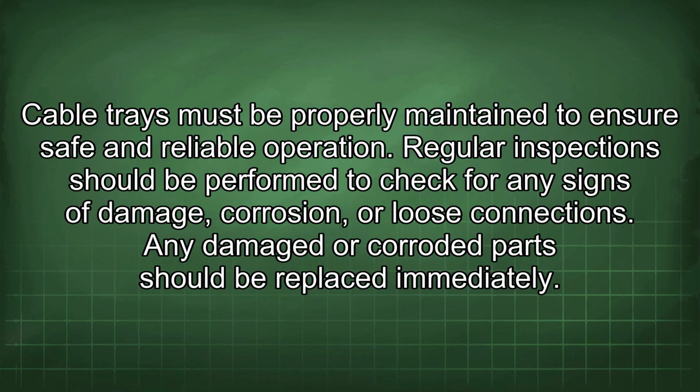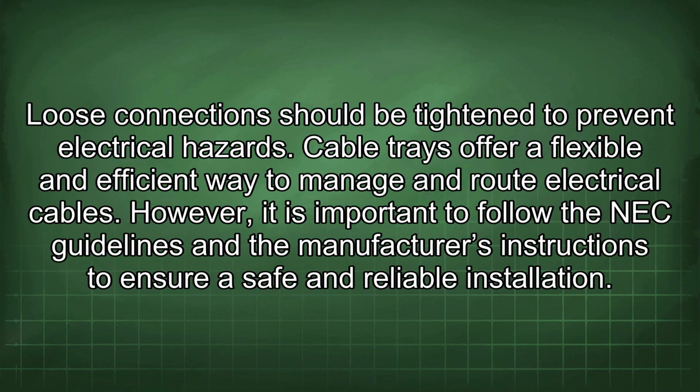Cable trays must be properly maintained to ensure safe and reliable operation. Regular inspections should be performed to check for any signs of damage, corrosion, or loose connections. Any damaged or corroded parts should be replaced immediately. Loose connections should be tightened to prevent electrical hazards.